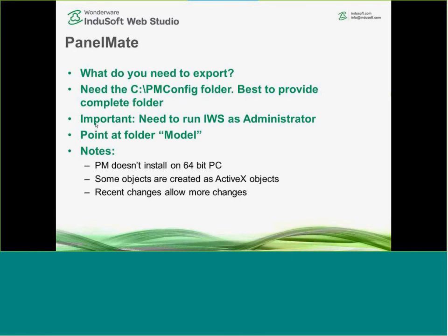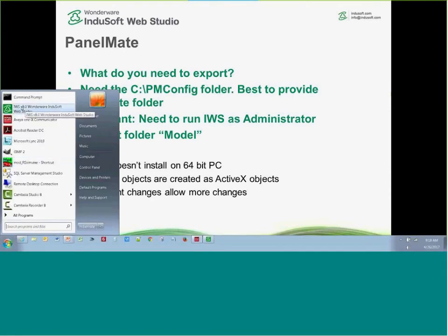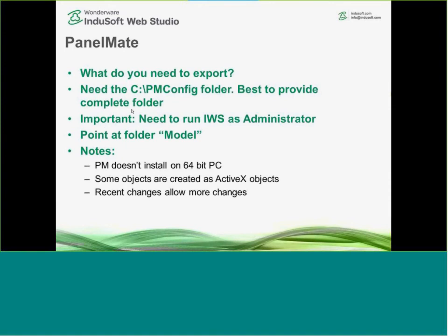The next thing is that when you run this tool, it's very important that you run InduSoft Web Studio as administrator. For those of you who don't know how to do that, when you have InduSoft Web Studio here in Windows, you can just right-click and then run as administrator. If you don't run it as administrator, it will not allow you to see the different projects in your PanelMate config folder.